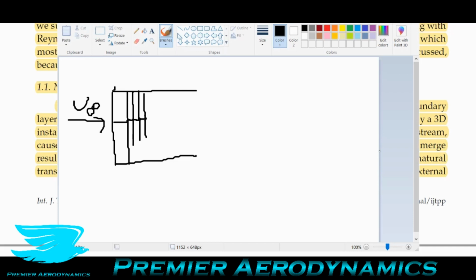And this is something that's very interesting with turbulence, that a two-dimensional phenomenon can break down three-dimensionally. That's a cornerstone of boundary layer transition phenomena. And for a long time, it wasn't really believed, but it was proven a few decades ago that three-dimensional effects do occur from two-dimensional effects, and we don't need a three-dimensional disturbance to get three-dimensional turbulence. Pretty much everything that's two-dimensional will break down three-dimensionally, unless the viscosity really tears it apart and suppresses it. But let's assume that the Reynolds number is high enough that the viscosity will not suppress this perturbation, and this perturbation will start to develop.